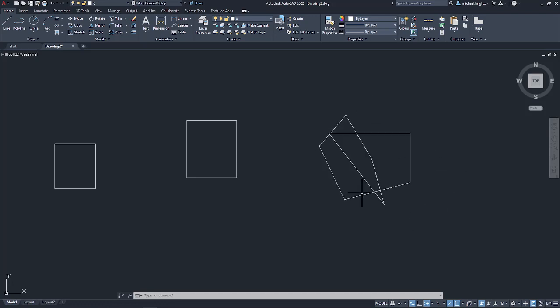So like I say, it's a lot easier using polyline if you want to create joined up objects than it is using line and then joining them together. You can join them together, like I said before. P-edit, so PE is polyline edit. Select polyline. Do you want to turn it into one? It says yes, it says no. So you say yes. And these are all the different options you have for a polyline. There's a lot of things we'll go through with spline, decurve and all this.